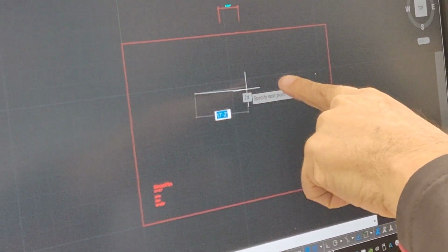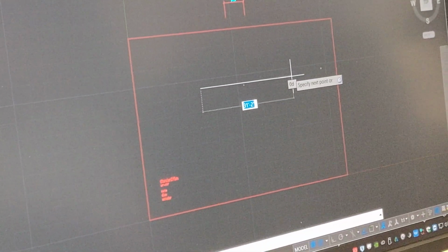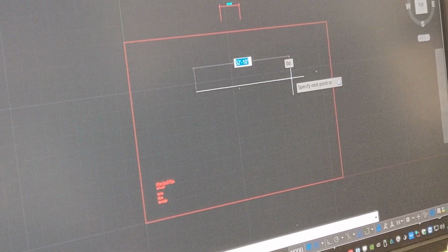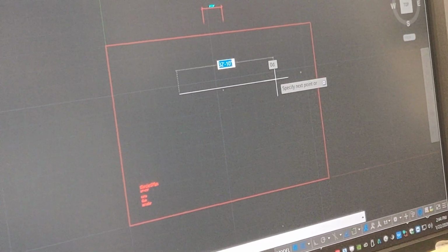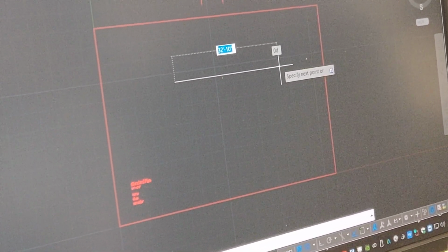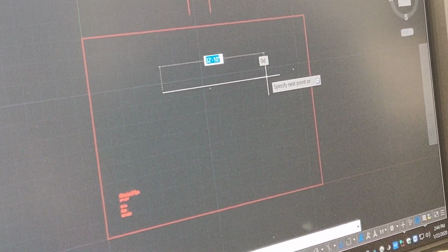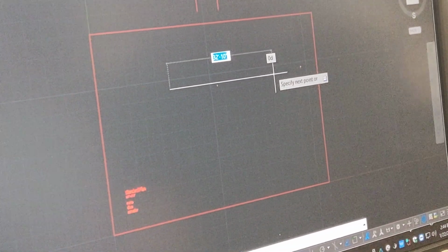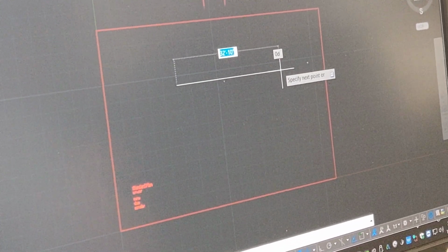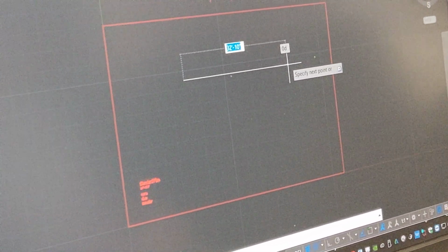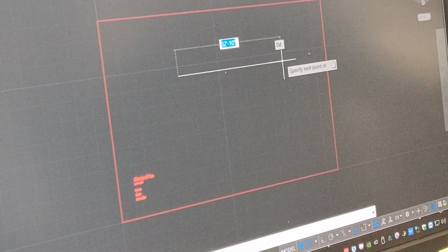15 foot 2, whatever, and so you can take it out. Now, if you're really good, you can hold this to where it says 0 degrees, right? And so if you get it going 0 degrees, and I want it 22 feet 6, which is 22.5 feet, right? Okay. AutoCAD automatically assumes inches unless you tell it different. So if you put 15 in there, it's going to assume you mean 15 feet. If I put 22.5, it's going to assume I mean 22.5 inches, unless I tell it feet. So make sure if you're doing feet, you put the foot mark in with that, okay?